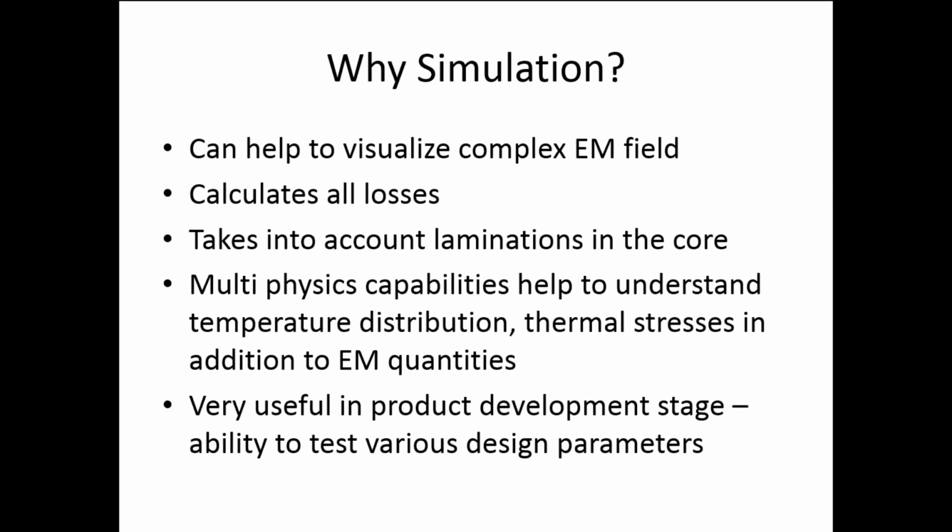Finally, some amount of multiphysics capability is available in the simulation. Right from the electromagnetic field, the induced currents are dissipated as heat. So one can compute the temperature distribution in the model, and from the temperature distribution, one can also compute things like thermal stresses, displacements, strains and so on.